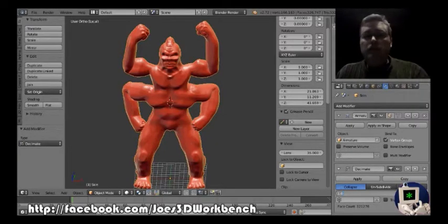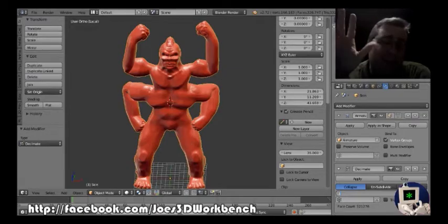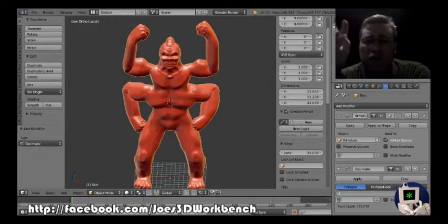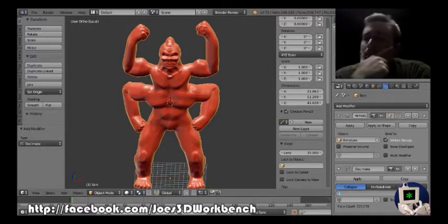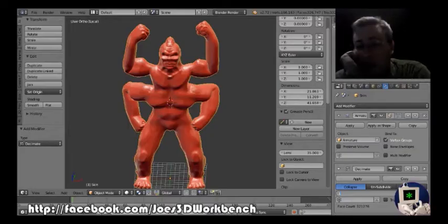But the major culprit is right here in the skin. So let's attack that first. Let's take it down to a 0.1 decimation. 1/10 of the polygons are going to be in this when the decimate modifier is done with it than were when we started. So let's see what happens.